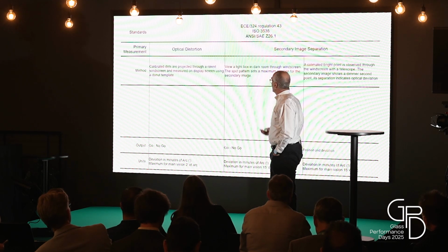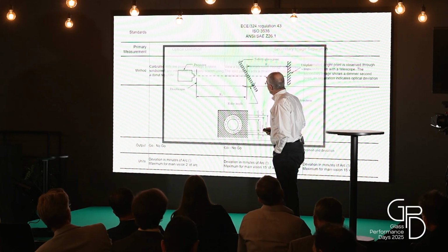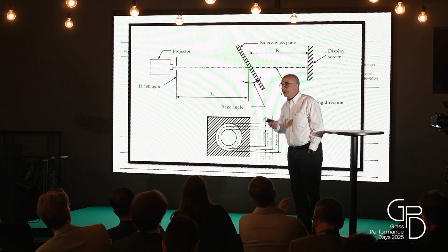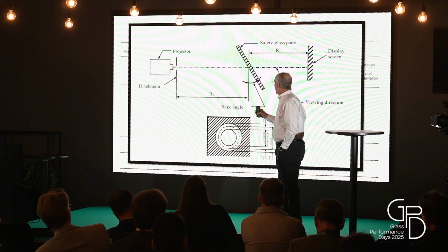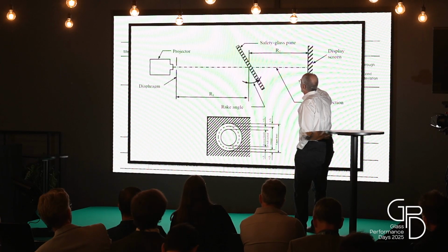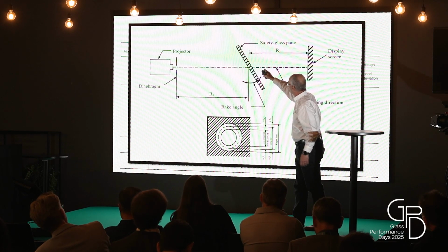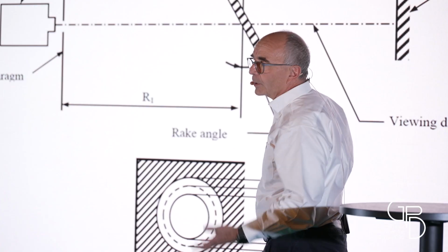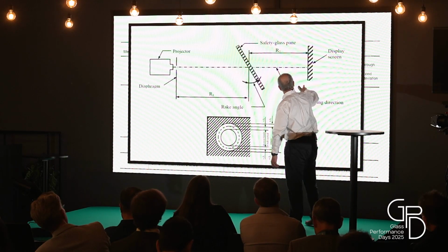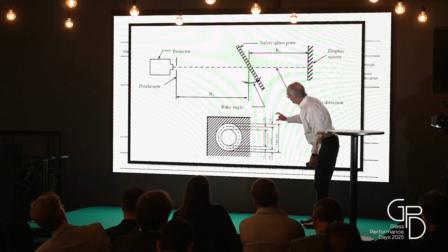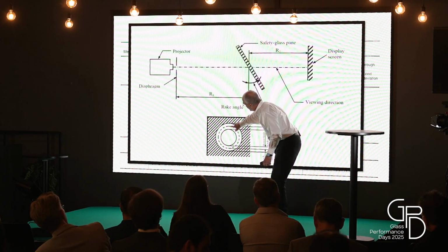It's a public document. So there are 2 things that they look at: the optical distortion, and the way they evaluate it is they take a projector with a slide with little holes in it, and 9 meters away or 7 meters away, you have a screen where the dots go, and you put the windshield or whatever piece of glass you want to test into the path, and you come to the screen, and you have a little target that you put on each dot, and you can see if it falls within this, you're good.